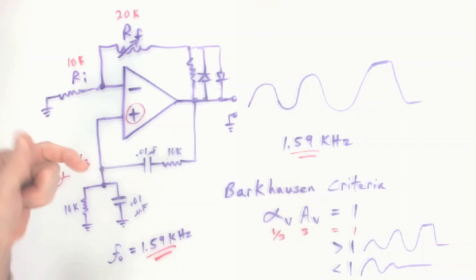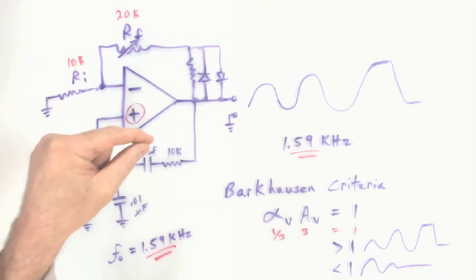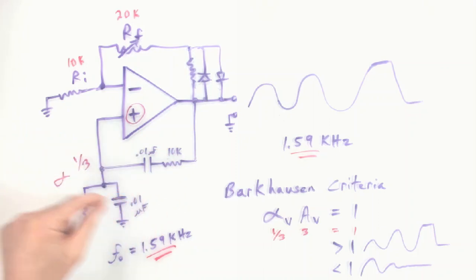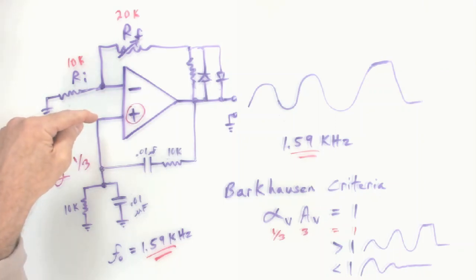Because you'll see phase shift oscillators that use a network that does have phase shift, but it all adds up to 0. If you have multiple phase shifts through your network, that the net phase shift is 0. That works. So as long as it's in phase when it gets to here, and meets the Barkhausen criteria and so on.